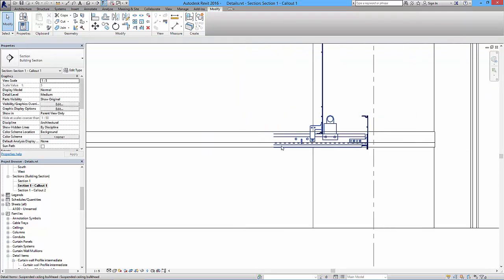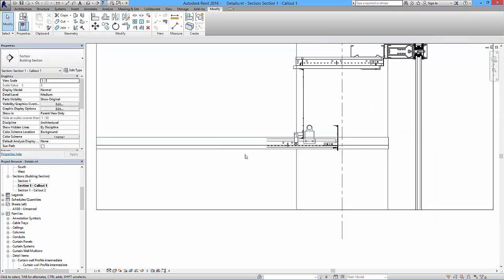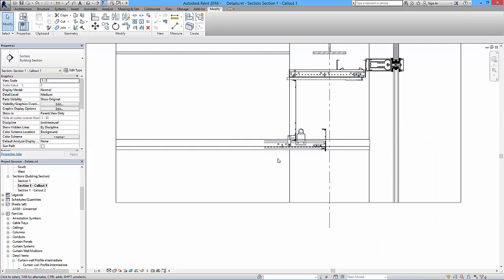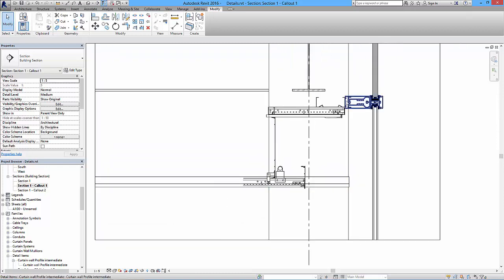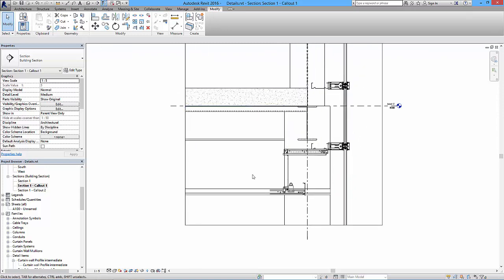And the important thing, even though we're going to hide this suspended ceiling, is that we get all the heights right to match up with our detail. There's no point in having the general model and the details being completely disassociated. We need to make sure that all the general stuff works as far as the details go, and what we do in this 2D drawing is just to add more information to the drawing.